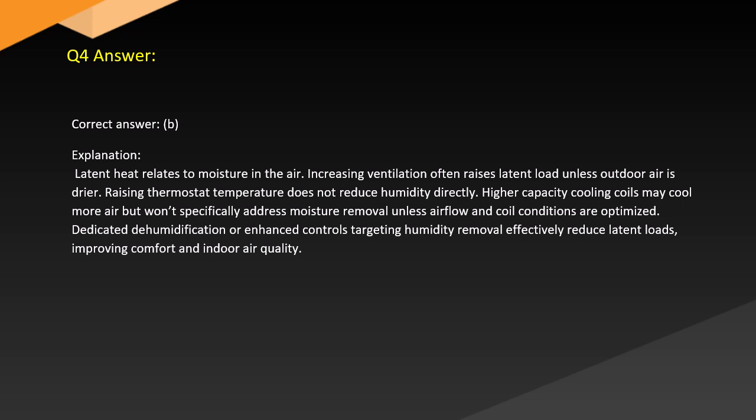Higher capacity cooling coils may cool more air, but won't specifically address moisture removal unless airflow and coil conditions are optimized. Dedicated dehumidification or enhanced controls targeting humidity removal reduce latent loads, improving comfort and indoor air quality.